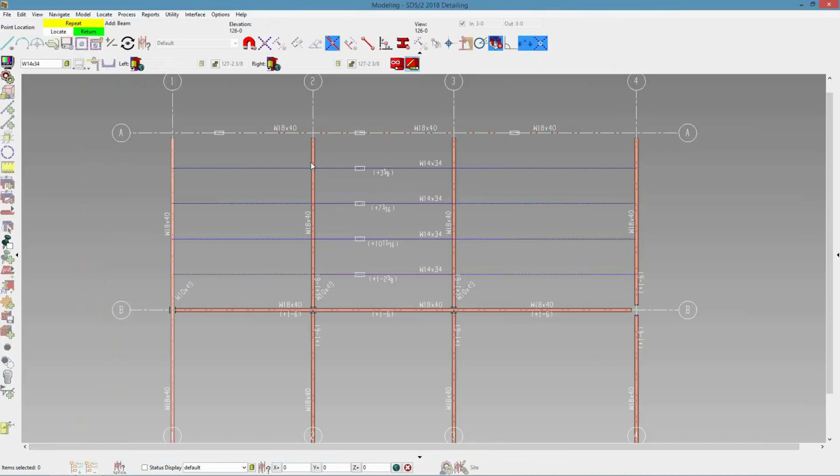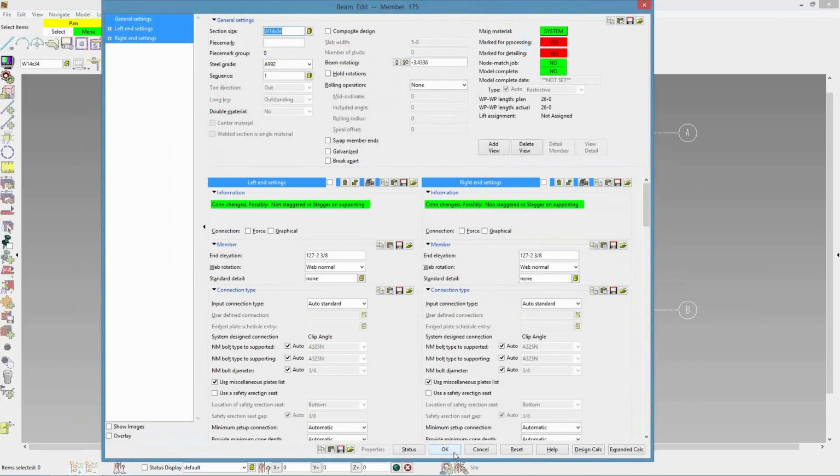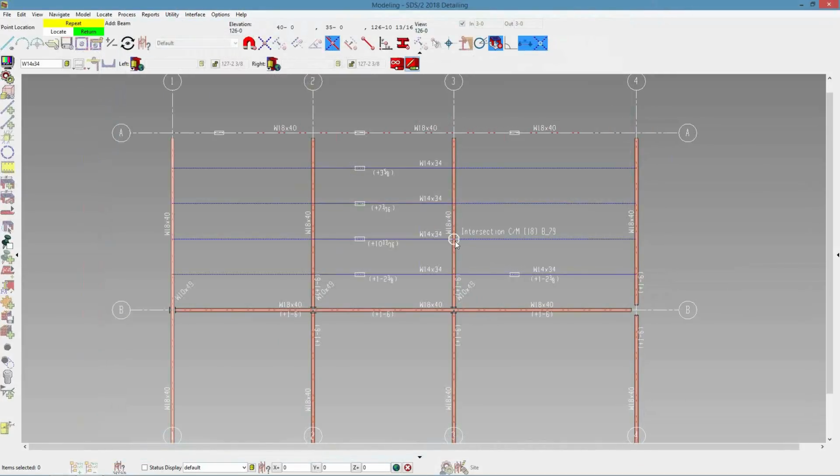along that beam. Now the advantages of the member add options bar over the repeat is when I move over to my next bay. It is a different span, so now I'm still in my member add and I can select my 2 points. It's going to follow everything that is on the member add options bar and say OK. And I can repeat down that line there. So the member add options bar can be used when there are different angles, different lengths, or when you need to change direction.